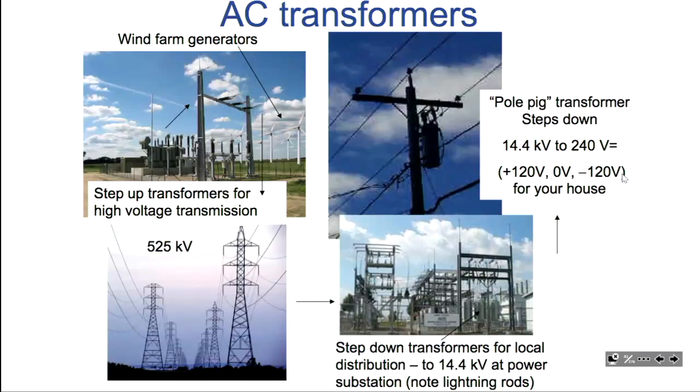And when we need to produce electric current, we use power plants. They produce very high voltage, potential difference, very high voltage EMF. But it's not high enough to transfer, because as we know, the energy loss depends on electric current, I squared times R. So we want to decrease the current, we want to increase the voltage as high as possible, and then make it travel through wires to decrease the loss of energy.